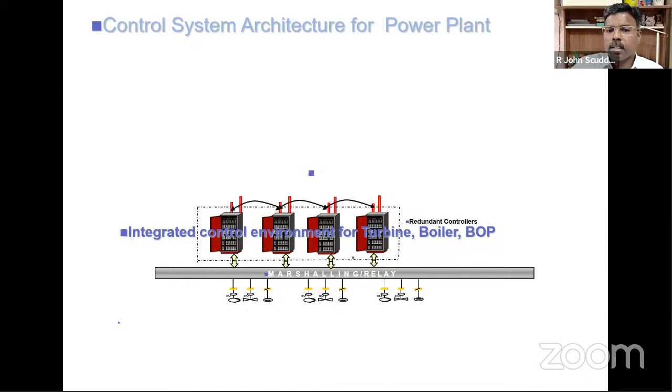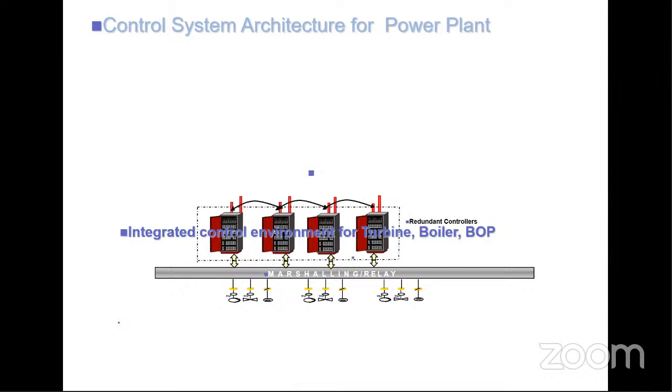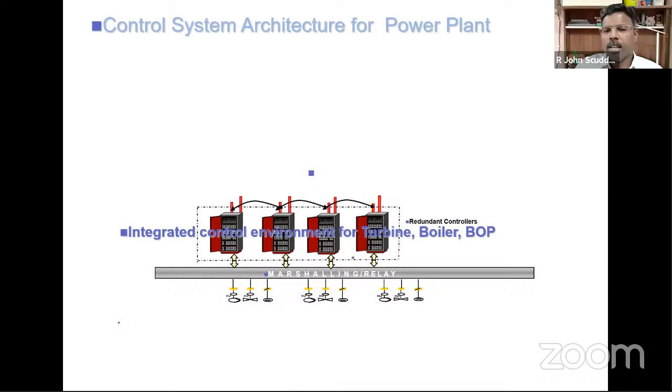So 12 milliamperes will come to the control room, to the analog input module. The analog input module receives that current from those two wires in which it sent the power supply. As I told you earlier, there are modules which do the analog to digital conversion, and that conversion turns this analog current value into a value understandable by the DCS.